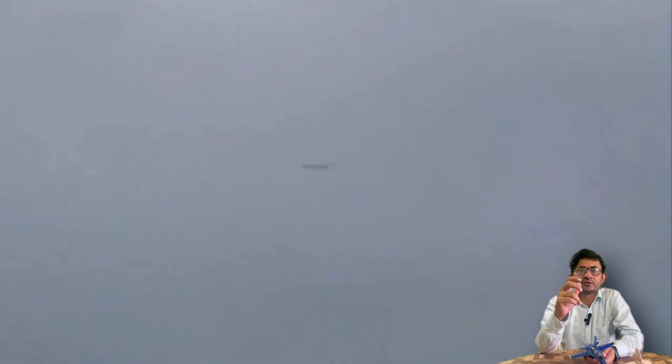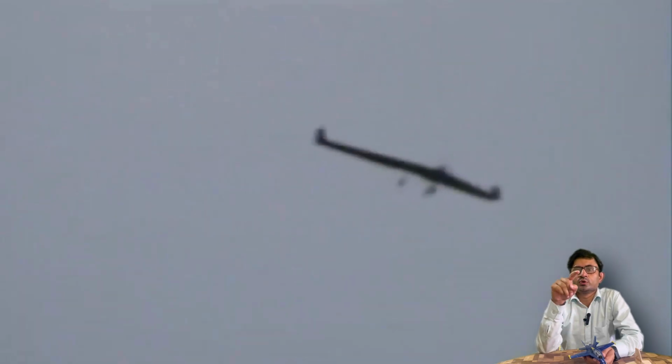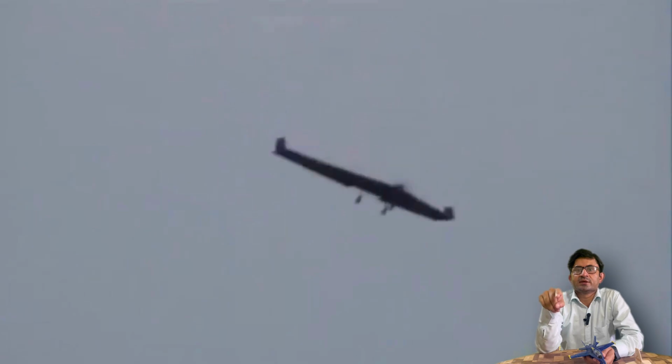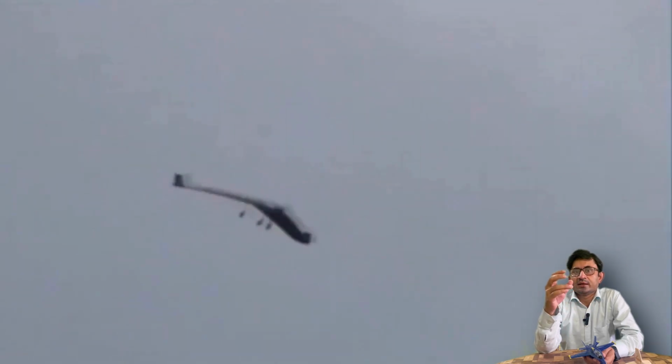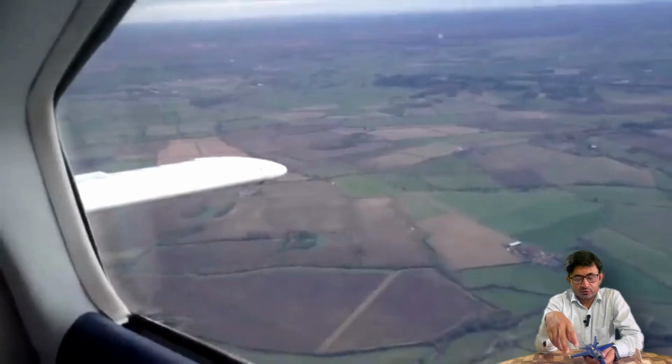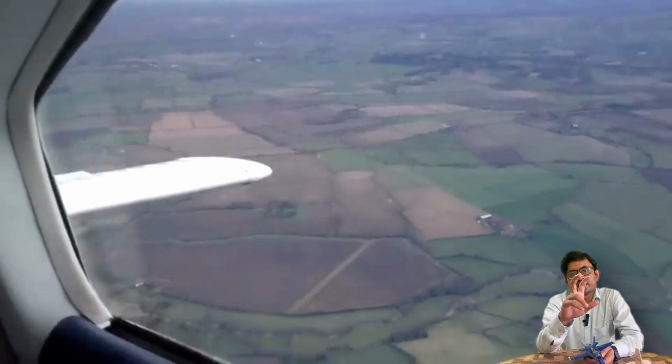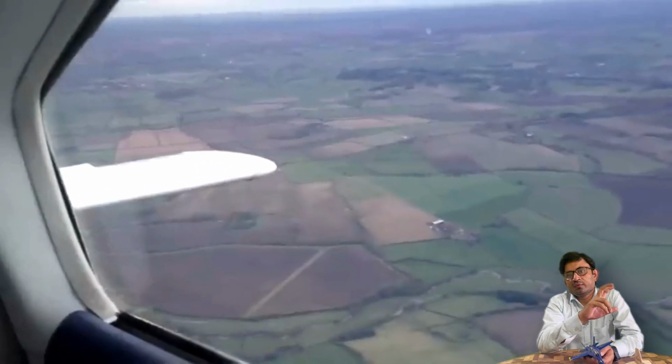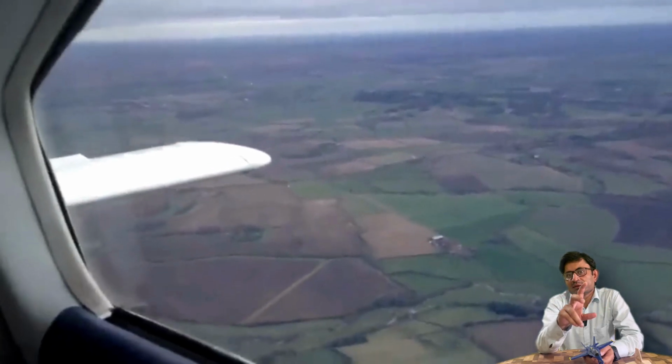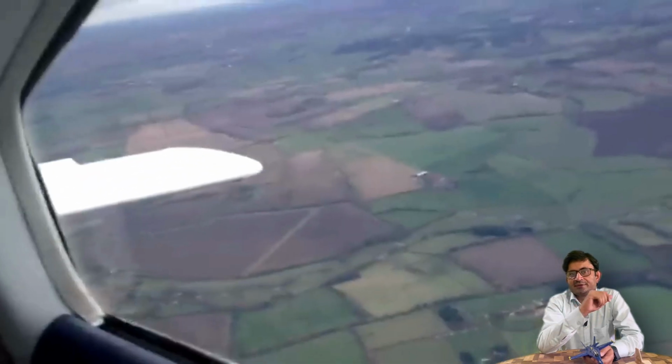And then due to the elasticity effect, again the angle of attack increases. So this phenomenon keeps going on. Amplitude slowly increases, leads to vibration, and then at one stage it leads to flutter. The wing and control surfaces can break completely, leading to catastrophic failure. So here you can see that flutter can occur when there is a coupling between aerodynamics, elasticity and inertia.